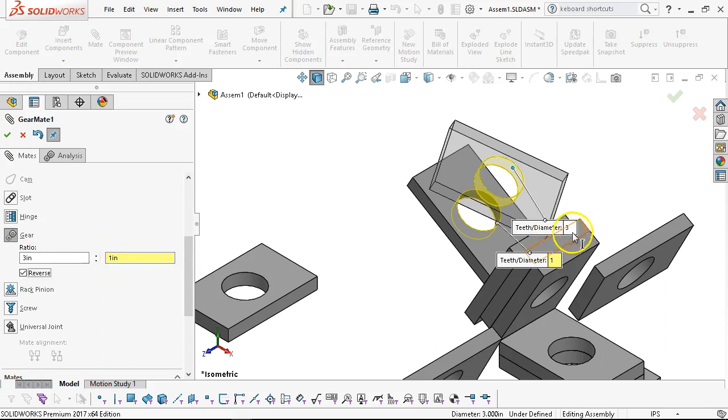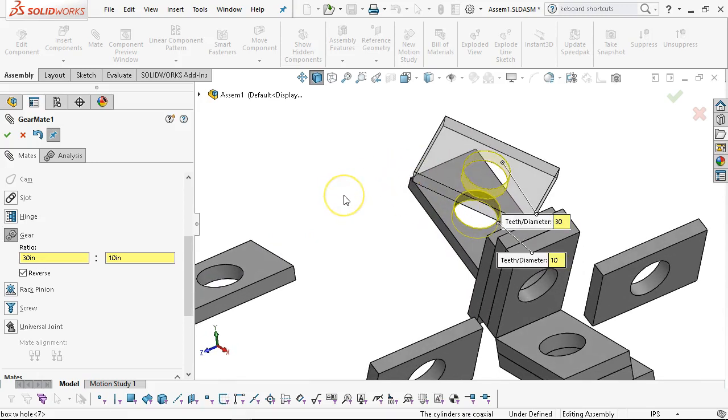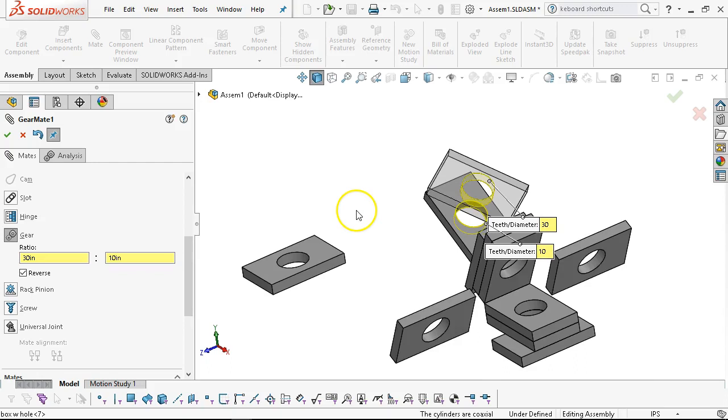So teeth, diameter, so, well, can't really have one tooth, can I? All right, so if we're in teeth, so 30 teeth to 10 teeth, not sure if that works out on the pitch, but basically whatever this one turns, and that's not going to be a concentric thing, is it? All right, I'm not in alignment for a gear. These pretty much need to be tangent and would typically make the pitch diameters tangent so that when one turns, the other one's turning faster or slower.